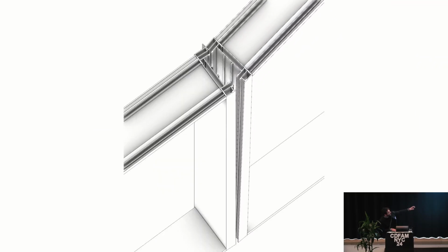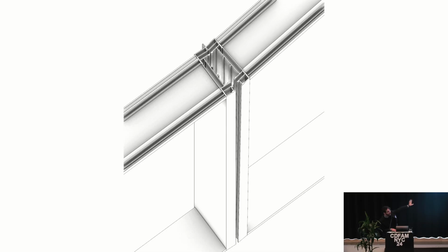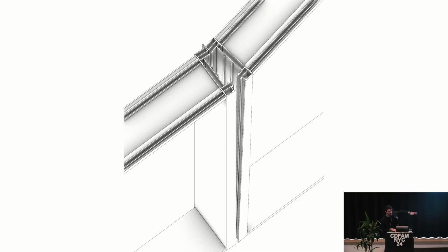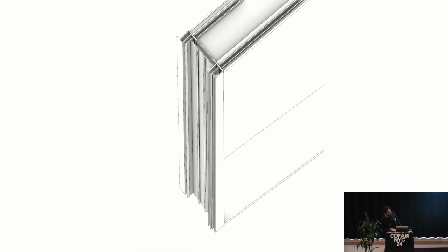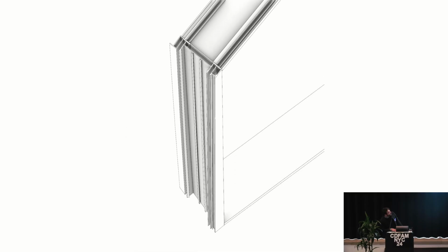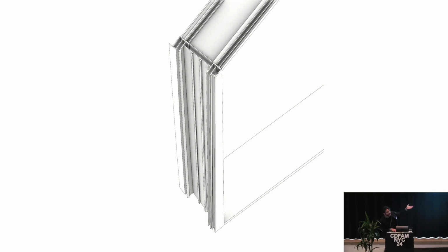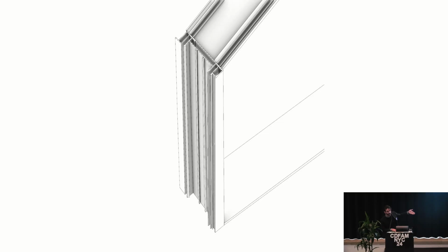Here's a version of it. So you push that panel into place, you think it's all well and good, and then you push the 4th corner, and now you've compromised the engagement between these 2 pieces. Not gonna work. So what's the solution? The alternative is you actually fix the top edge in place and adjust the angle of the cut on the end, and then you can dial in the amount of twist in that element.